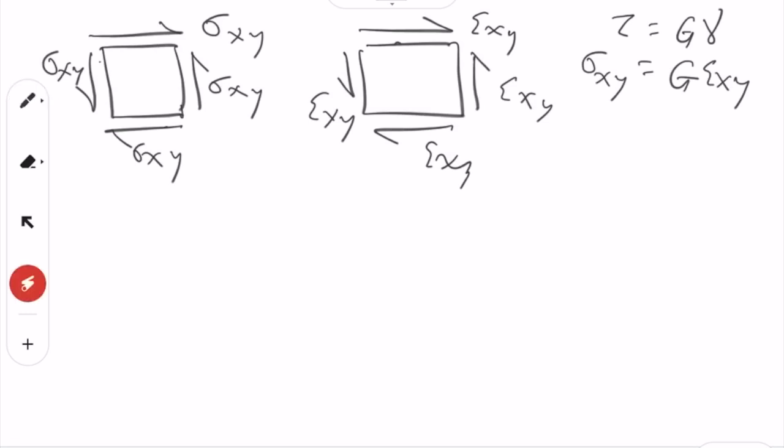Here also this is shear stress, this is shear stress, this is gamma shear strain, this is also shear strain. There is a difference between the two though. This is talking about the engineering strain, engineering stress. Here it is a little bit different notation. This is called Cauchy stress. But basically this is actually the same thing.